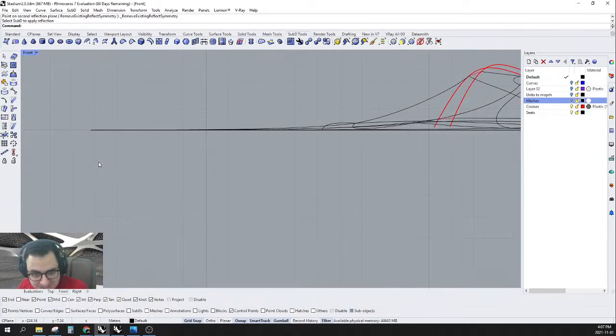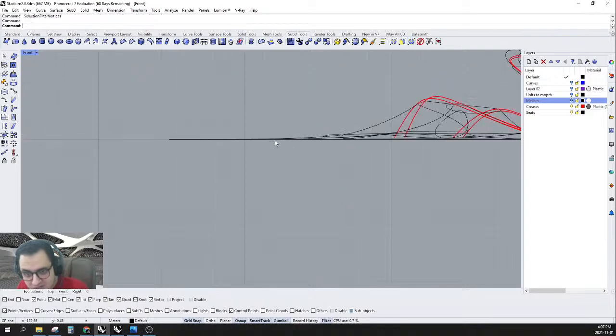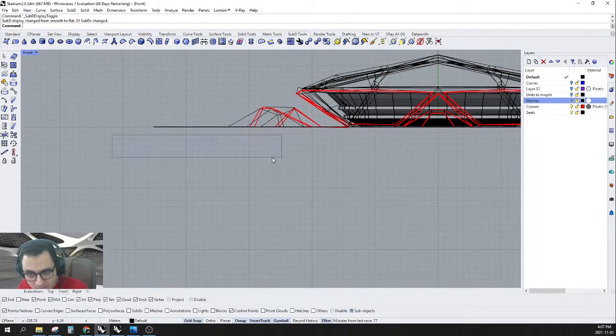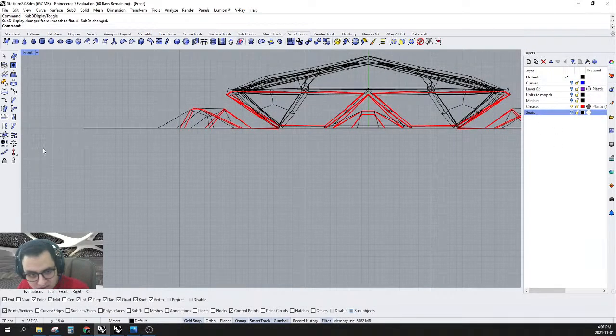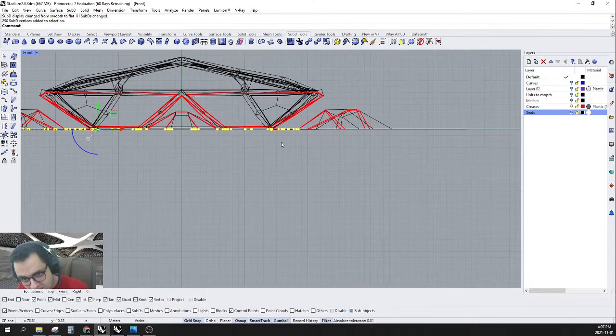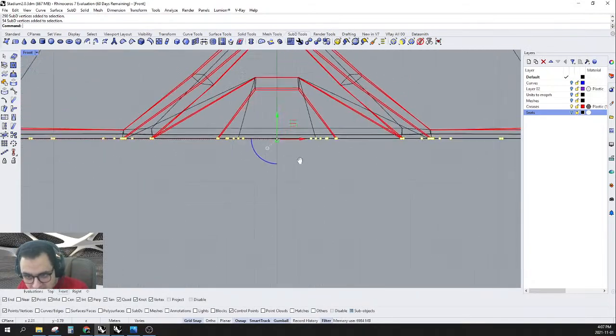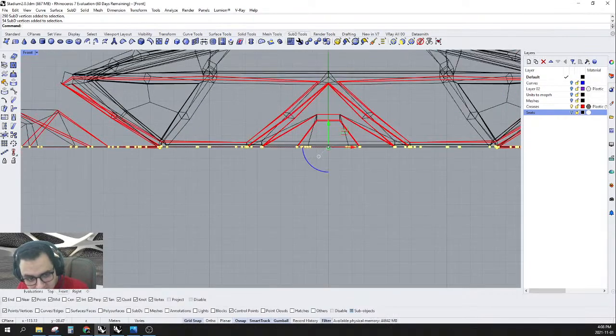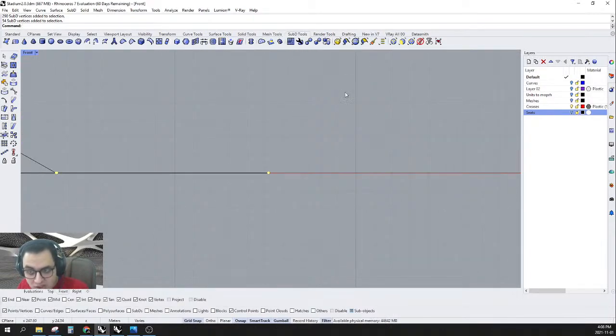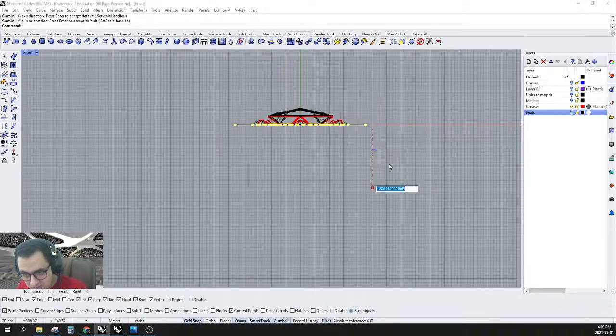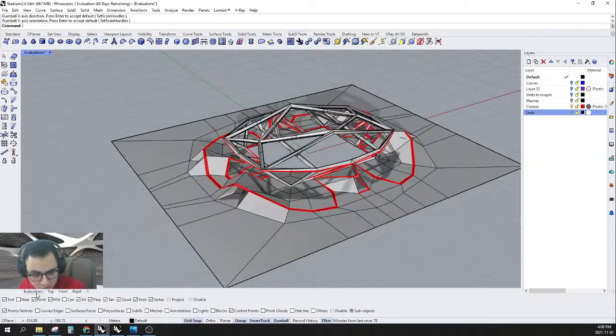So now we can select everything, every vertex in here. Just make sure, move like this and hide the seats, because the seats are not welcomed in here. Okay, and simply select all of the vertices in the 0 level like this. Just make sure that you are selecting the right vertices. Okay, and after that again Gumball relocate. Okay, and simply 0, so they will be totally leveled.